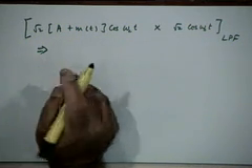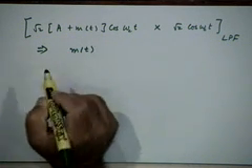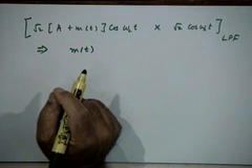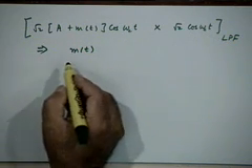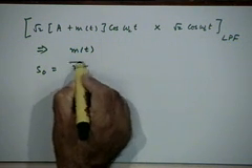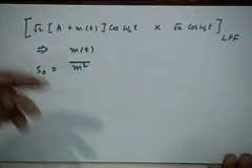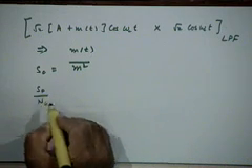No, the A part is not message, right? So the message part is only m(t), right? So really speaking, you will get m(t) as far as the signal part is concerned. So your output signal power will once again be equal to m square bar, and as far as the noise is concerned, there is no difference, right? So what can I say about S naught by N naught?